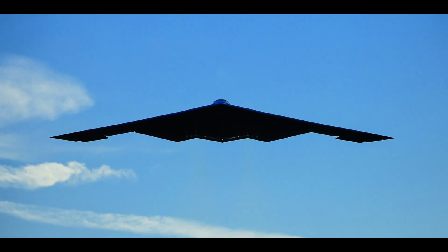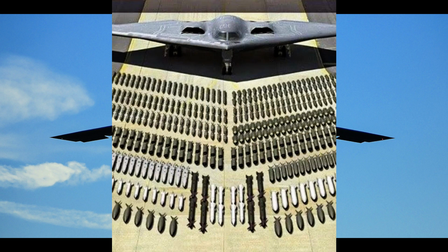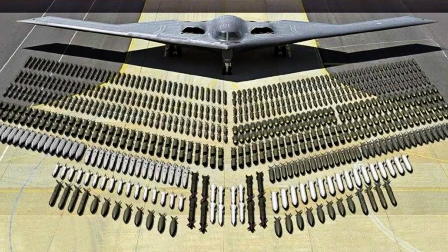A more important advantage is that a very smooth, compound curved, aerodynamic structure made from composites reduces drag. This is the main reason sailplane designers switched from metal and wood to composites in the 1960s. In aircraft, the use of composites reduces drag for the Cirrus and Columbia line of production aircraft, leading to their high performance despite their fixed landing gear. Composites also help mask the radar signature of stealth aircraft designs, such as the B-2 and the F-22. Today, composites can be found in aircraft as varied as gliders to most new helicopters.